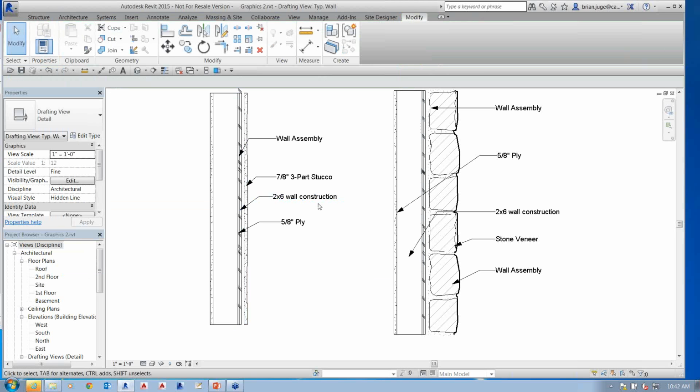It automatically changes out. And by the way, for create similar, you can also just type in CS if you're more of a keyboard shortcut type man or woman. Sorry, I'm not getting to all those things in there, but this really gives us a nice quality. All I drew was a line, and with one line I'm able to draw a whole wall assembly in here and start changing it.